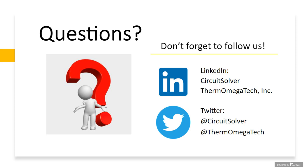There are a number of different valves out there, different solutions where you can install these, and what they'll do is combine your cold water line into the drain and use a paraffin wax actuator to sense temperature. When it sees that there is too high a temperature going to these drains, it will open up and allow cold water to flow in, mix it down to under 140 degrees, and make you compliant with codes. So that is one solution.